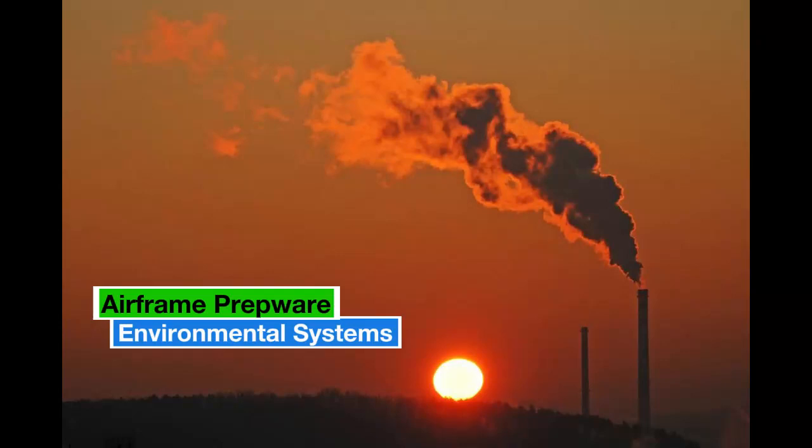How can it be determined that a vapor cycle cooling system is charged with the proper amount of Freon? Air bubbles in the sight glass disappear. What is the condition of the refrigerant as it enters the evaporator of a vapor cycle cooling system? Low pressure liquid.